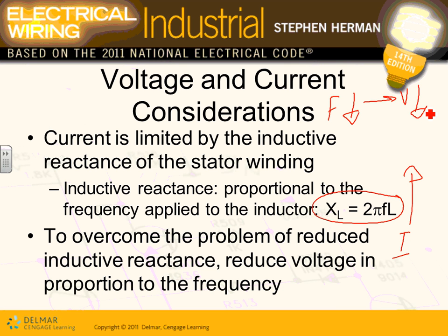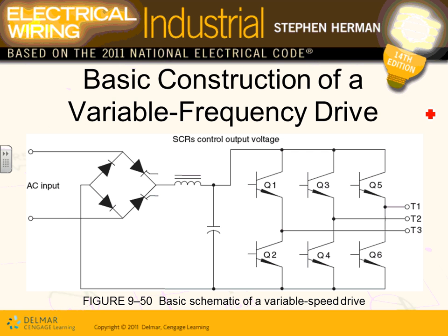Can I hear that, guys? Reduce voltage and frequency to reduce the motor speed. Because if you reduce the voltage only, you will burn your equipment.